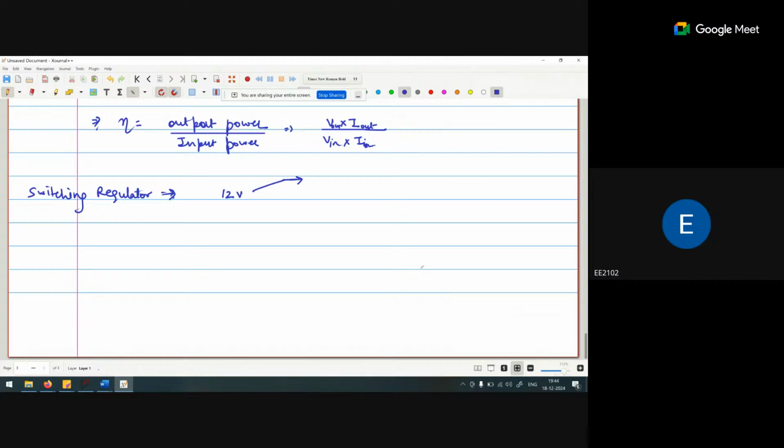Okay, so if I say that my AC will be working for 12 hours, I can't say that for the complete 12 hours the AC will be using 1.5 kilowatt-hour units. That is not compulsory. Initially maybe it will require 1.6 kilowatt-hours. After that it will reduce because my room is chilled now.